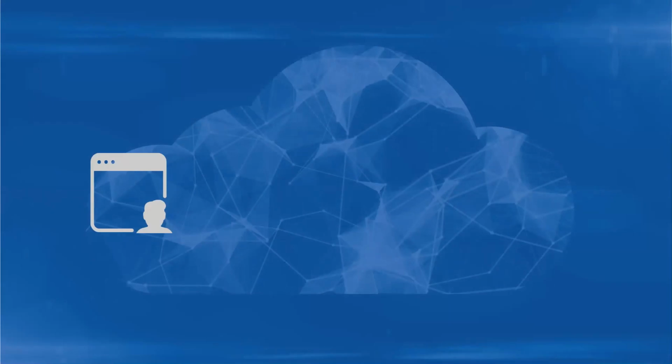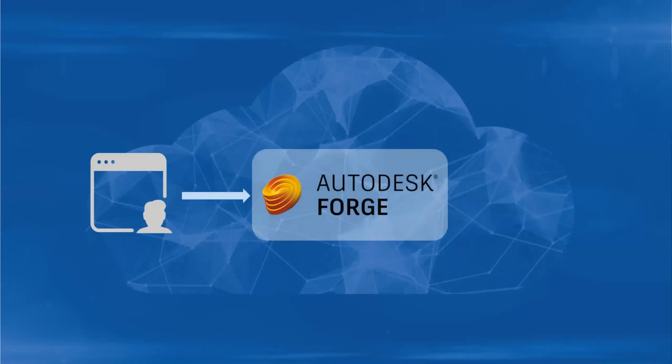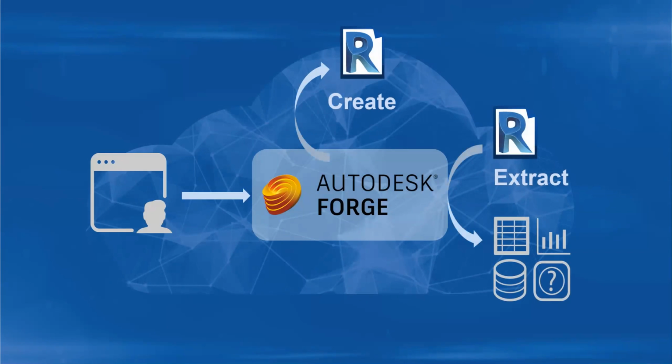The way this works is your app would submit a job to Forge and request that Revit.io process some information. Then Design Automation can create a Revit file based on data that you specify. It can take a Revit file and extract data to whatever format that you're defining, and you can start to use that data to create charts or put in a database. It's really up to you how you use that data.